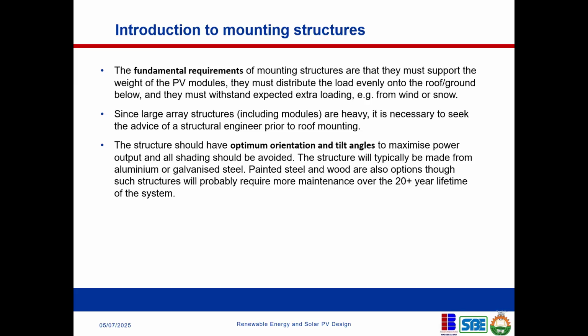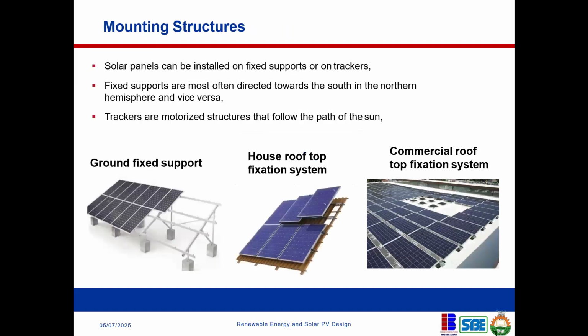And the reason is because these solar panels you're mounting are expected to last for more than 20 years. Now, if you use wood, it can easily degrade because of exposure to the climate. It can easily degrade before that 20 years. And what are you going to do? Do you have to go and remove them? So it does not actually make economic sense to use wood as a mounting structure. Okay, so it's ideal to use galvanized steel that can last the lifetime of the solar system.